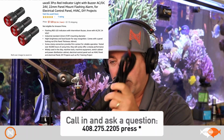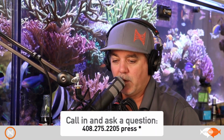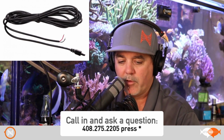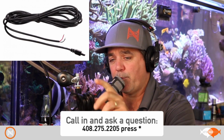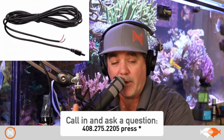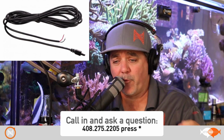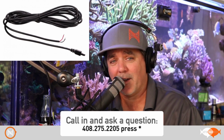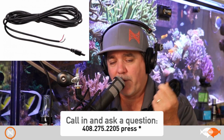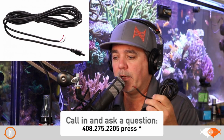you will need one of these cables. This is the DC24 cable, and you can get that from either your online supplier or from your local fish store, whichever you have. I will say it's probably a little less available at your local fish store because it's not a super common thing to have. Also, one thing really cool about it: if you do have a 24-volt fan, now realize if you put a 12-volt anything on this, you could poof it, right? So make sure it's a 24-volt DC device. But if you have a 24-volt DC device and you want to plug it in, you get this cable.